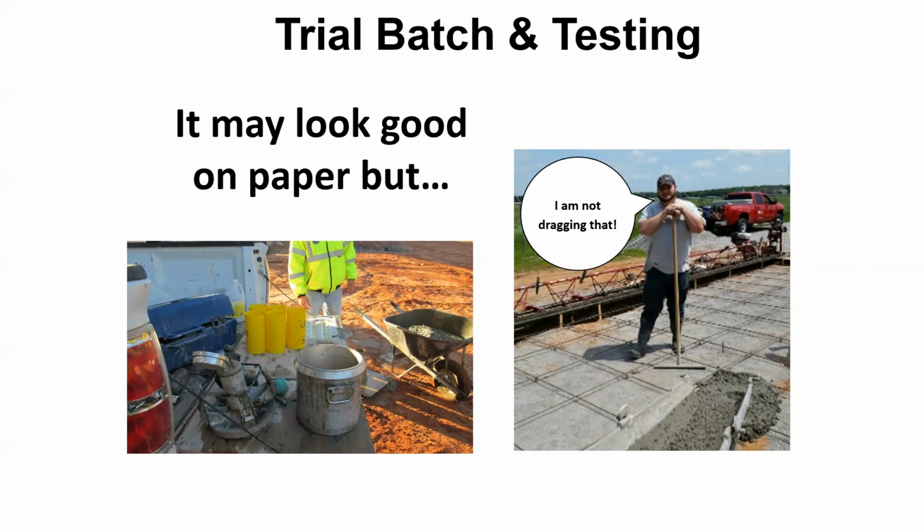When you design a concrete mix, go out and actually see how it looks when it's being placed, when it's being finished. Not just the cylinder breaks, not just the test results, but see how well people can actually use it. And then go back years later just to look at it.